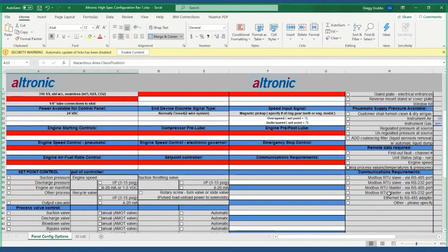And if for some reason you don't know how to ask or know what the terms are, they'll be asking you some questions, whether your Modbus is half duplex, full duplex, 2-wire, 4-wire. Feel free to pick up the phone and call and ask. Just say, I don't know. Let me get back with you. The key is first asking the question, but second, getting the correct information. If we get the correct information up front for all the things we need, the project's going to go very smooth.